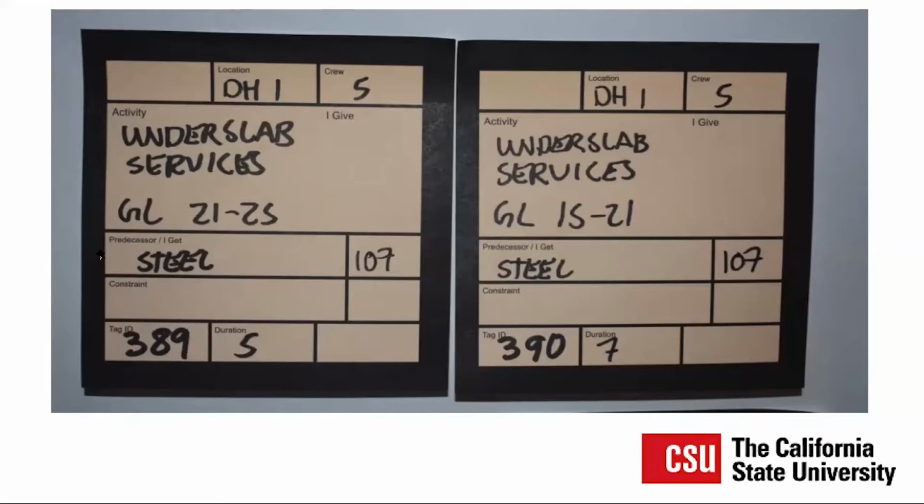The predecessor is, what do I need before I can actually do my work? In this case, they need to have the reinforcing steel. This number here is the tag number for that. There's a tag ID, and I wouldn't get too wrapped up in this, but some teams use tag numbers, some don't. We like to use them because it makes certain that people clearly identify the handoffs, either from their own work or from other trades. But this is really nothing more than a license plate number. And then the duration, this is typically days, and sometimes it could be hours if you're using this for a shutdown or something along those lines where you had a very short duration.